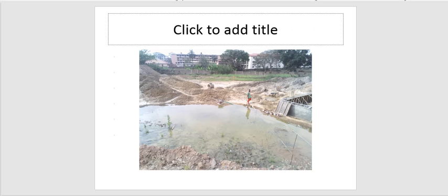Can you see? We graded a lowered area, and the water collected, and as the water collects day by day, we keep pumping it out. So the ditches and sump method has been what we are using. I think it's relatively less expensive. Well, whichever one suits your site, and in case you give me a call and describe what you're passing through, I think I can help you tell what will help you out of that.